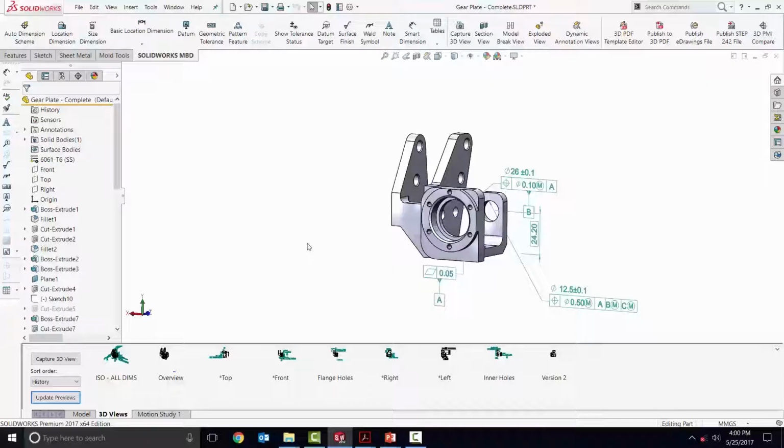That's a quick overview of how to create views and dimensions from within SolidWorks that we can then use downstream in MBD. As you can see, it's very easy to create these dimensions, simple to learn, and easy to use, and it's also using existing tools like DimExpert to allow you to generate that content directly inside your 3D model. What I want to take a look at next is some of the export capability once you've got all the dimensions created and how that information gets relayed downstream. So let's take a look in SolidWorks.